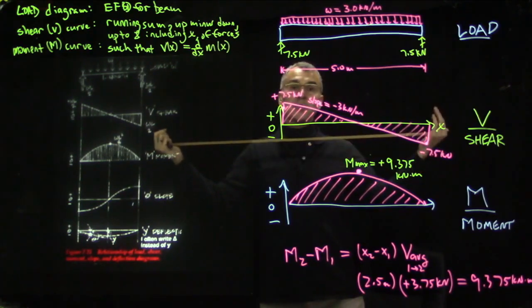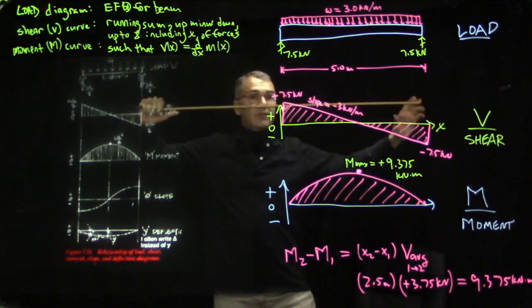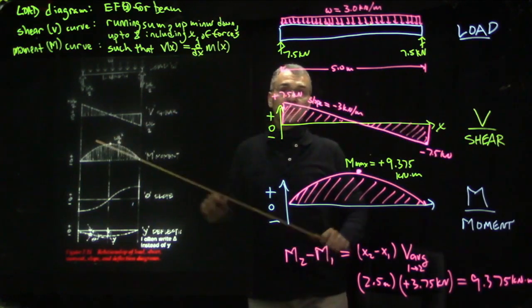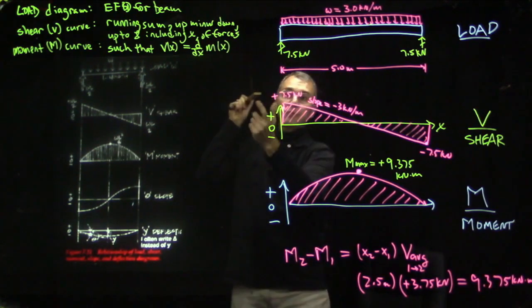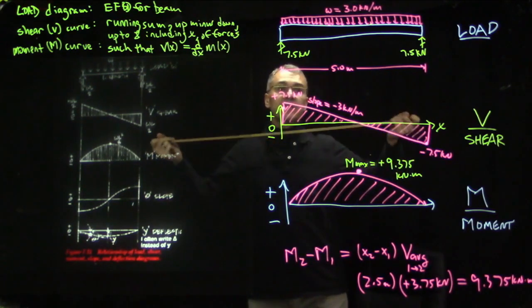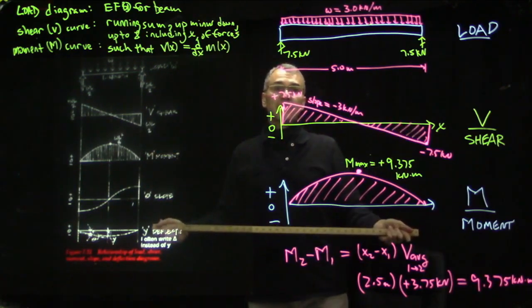So if you have a beam which is supported on both ends and is uniformly loaded, you expect a shape like this. And if you have a beam which is a cantilever that's loaded at the end or is uniformly loaded, then you expect a shape like this. We also said earlier that the stiffness of the beam is proportional to this second moment of area, which for example distinguishes a plank from a joist. And we said that we would later show that the deflection is inversely proportional to that second moment of area, I, but we just said it, we didn't prove it.